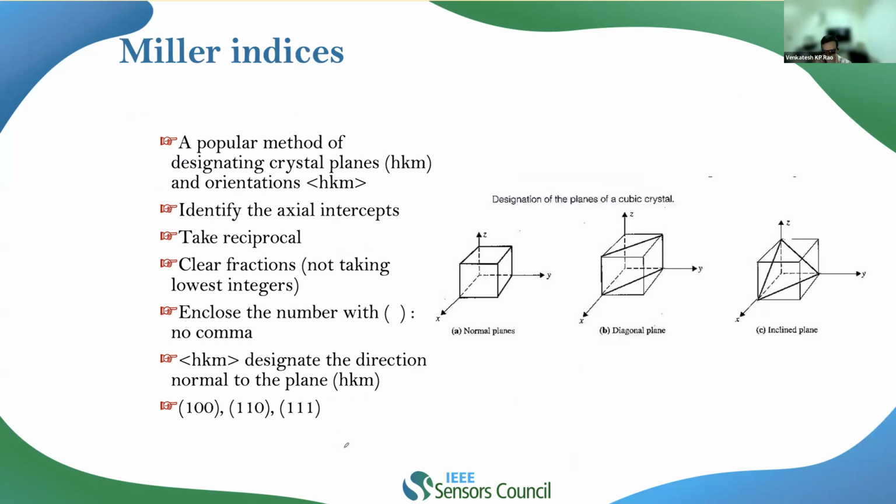As we looked into in the previous session, there are several orientations of single crystal silicon. It can be a 100 wafer, 110 wafer, or 111 wafer. The orientation of the wafer is decided by the Miller indices. Let us say you take a normal plane under consideration; it will intercept the x-axis at unity. This is basically a single unit cell, and all the dimensions are unity. So it will intercept the x-axis at 1, the y-axis at infinity, and the z-axis at infinity.